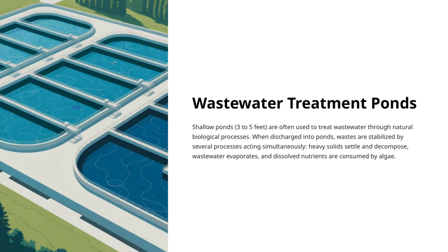Today, we'll explore how shallow ponds, typically 3 to 5 feet deep, are used to treat wastewater naturally. We'll look at the processes involved, like how solids settle and decompose, evaporation, and how algae help consume nutrients. So, let's get started and discover how these ponds play a vital role in wastewater management.